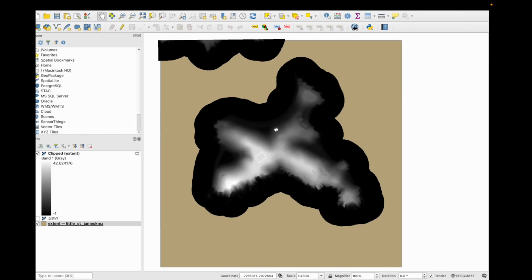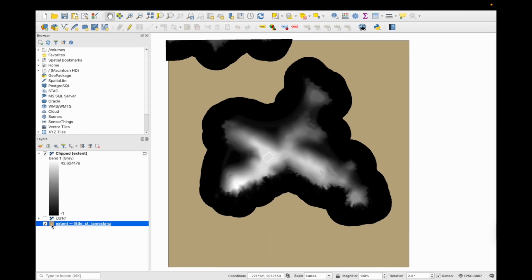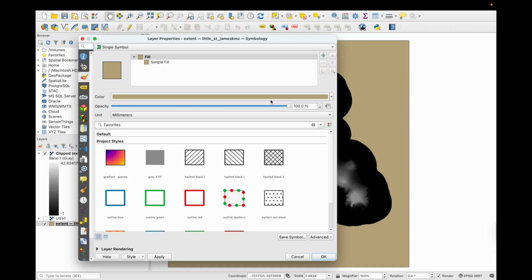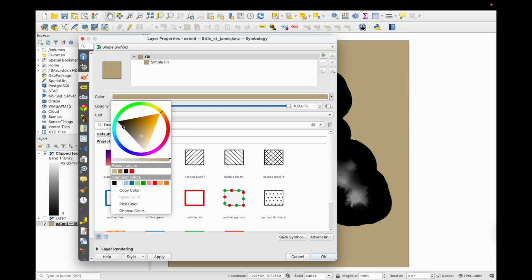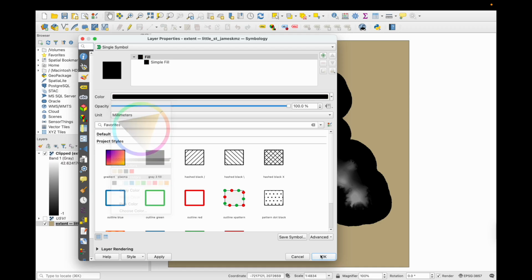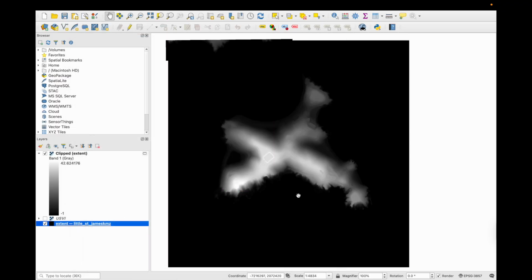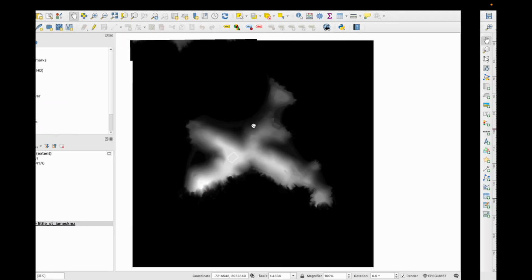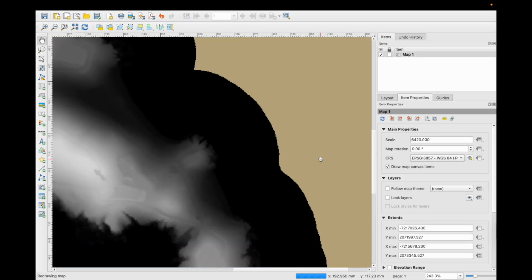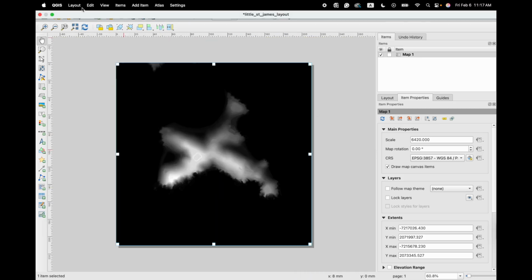So once we're done with that, go back to our map editing interface and change the color of our square to black. The reason is that black color in the context of DEM means the lowest elevation value. So in this case, the water surface. So even if the terrain that you're trying to import on your own isn't an island, I would still encourage you to do the same, because you just may never know if your data contains areas of no data, like we're seeing in this case.